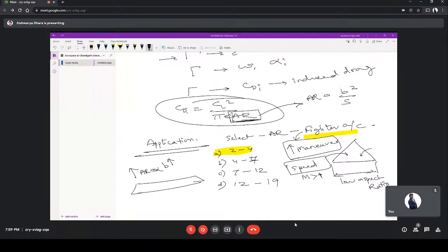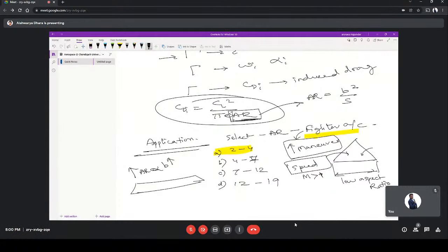And if it causes a drag and obstructions, it will cause a normal shock wave. From the normal shock wave, it can cause structural damage. So there's no point in having the structures if it leads to structural damage. So you're getting my points. We don't need a large span, we need a feasible one. So this 2 to 4 serves the purpose. Remember one more thing: the more the speed, the less the span.